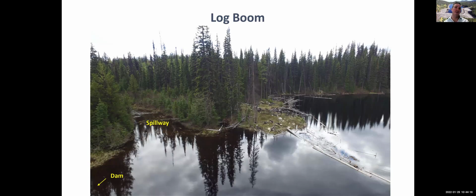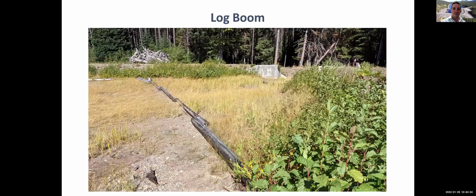And some spillways are designed to handle debris so that I wouldn't call them maintenance free, but they have limited maintenance. But if you have a dam like this, where you have quite a large spillway that can be impacted by debris and you have a lot of debris loading, you have to stay on top of your log booms. And if you've got a log boom and you're using that water in your dam, the fall is the perfect time of year to pick up all that stuff. You can see in this photo they carried all the debris over there. You can see it wasn't from that year. It's dried out quite a bit. It's probably ready for burning.